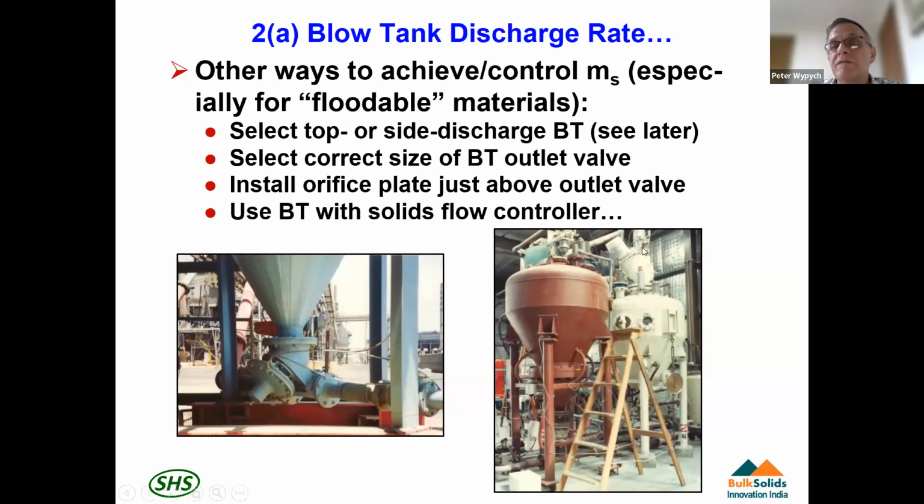And that's got the cone dosing valve there. And the one on the left has the electric box in there to do the same purpose, to control the frequency and amplitude of the cone dosing valve. When we did so-called normal blow tank discharges, we just take the cone dosing valve out and then we operate it like a normal blow tank. But anyway, just interesting how these were the first designs that were installed in our lab.